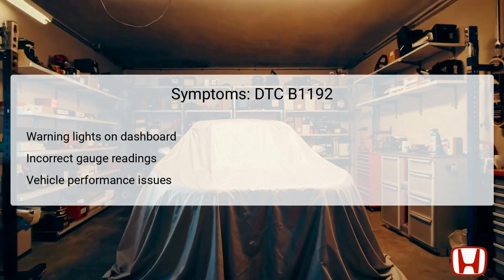Symptoms associated with the DTC B1192 often manifest as warning lights illuminated on the dashboard, indicating potential battery or electrical issues. Drivers may also notice incorrect gauge readings, particularly regarding battery charge and other related metrics, leading to uncertainty about the vehicle's operational status.